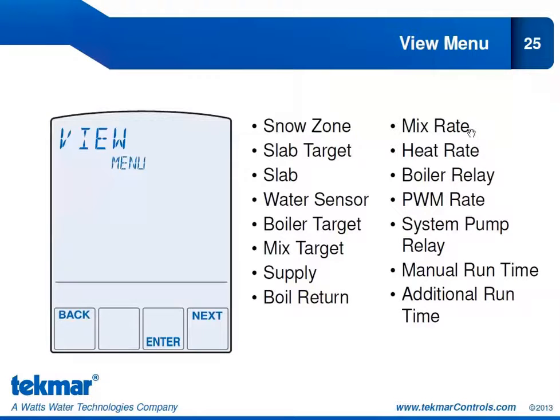So what position is our mixing device in? We can look at our heat rate. The boiler relay, is that open or closed? The PWM rate. The system pump relay, is that closed? Is the system pump operating? Manual runtime and additional runtime.